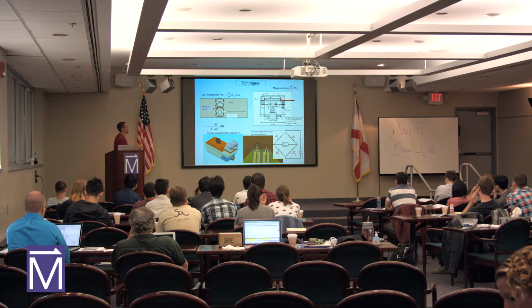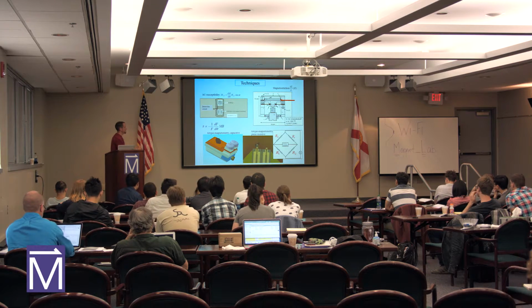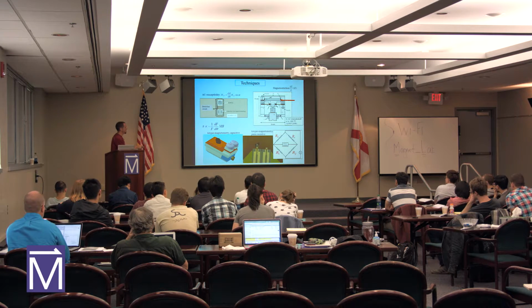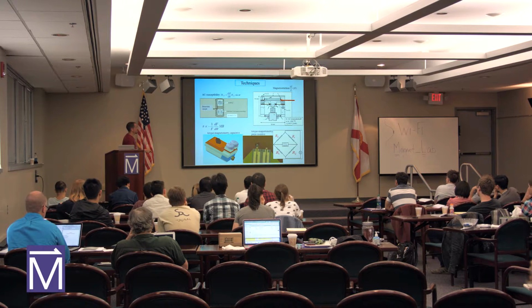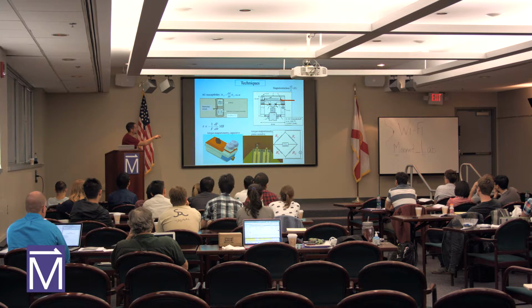This is the dilatometer that Eric was talking about, and I'm glad we have a schematic of it up here because it's a brilliant design. It looks really complicated, but it's actually a very simple idea. This is the reference to George Schmiedeshoff's paper, how he designed and constructed it. But if you look at this apparatus, it's just a parallel plate capacitor. This plate up here is fixed at both sides, and this lower plate to the parallel plate capacitor is resting on a foil spring, so this can move up and down. And this lower plate has a point that's touching the top of a sample, and that sample's fixed in place.